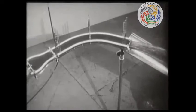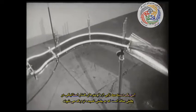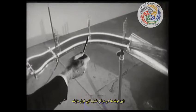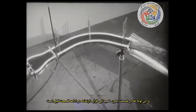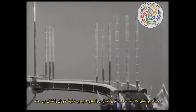In this bend, the streamlines are curved. This is a set of 3 static pressure manometers in the straight section approaching the bend. This set is in the middle of the bend, and this set in the straight section following the bend. In the upstream straight section, the streamlines are virtually straight, and the 3 manometers show no pressure variation normal to the streamlines.